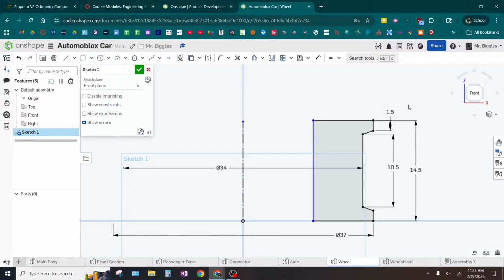So this is a little bit more difficult, but here's what I would do. You can try and measure the thickness of this. You can certainly do that. I don't have the best of luck with that because the outside isn't a solid surface and there's a curve there. You also, though, can use the upper teeth that measures interior dimensions and try and get the inside.